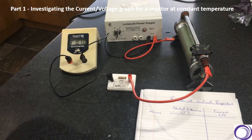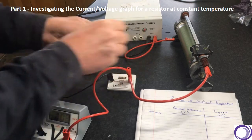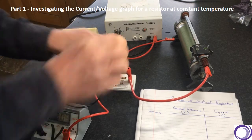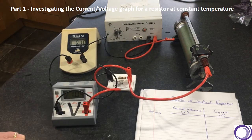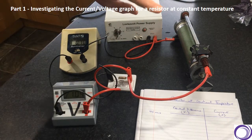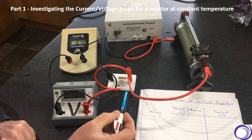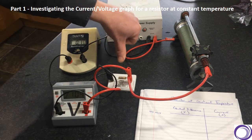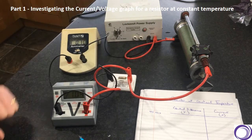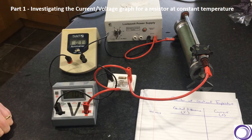Need to measure the potential difference as well though, so remember the voltmeter has got to go across the component that we're interested in. So it goes across either side there of the resistor. We can then take different values, first of all in the positive direction. I don't want to exceed that 4 volts there. If I get heating, I might damage that. It might potentially get dangerous, but also I'm looking at a resistor at constant temperature. I'm trying not to let this resistor get too hot, so I'm not going to do very high values.